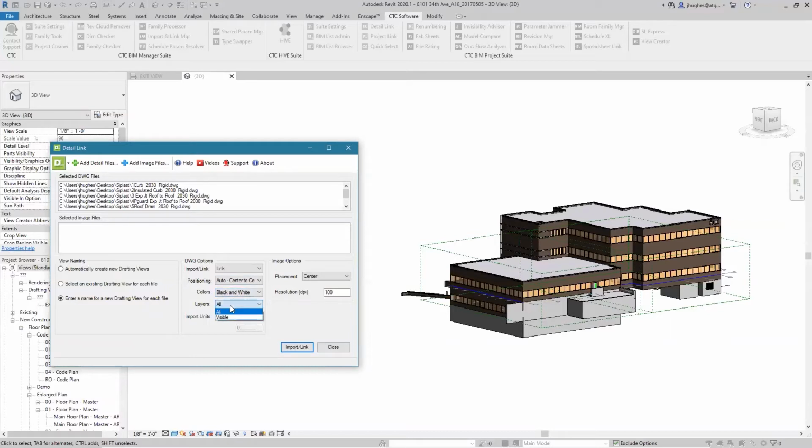With layers, it normally sounds good to choose all layers, but I can tell you, particularly with floor plans, when you bring those in, those were created by a professional, probably much like yourself. And I don't know about you, but a lot of times in my floor plan model space, I have brought in elevation views. I brought in all kinds of stuff because I don't always have the best drawing hygiene in AutoCAD.